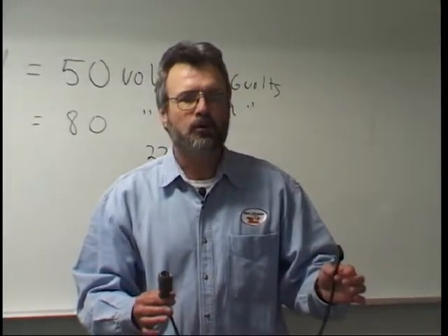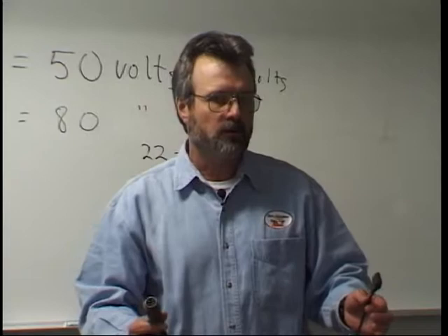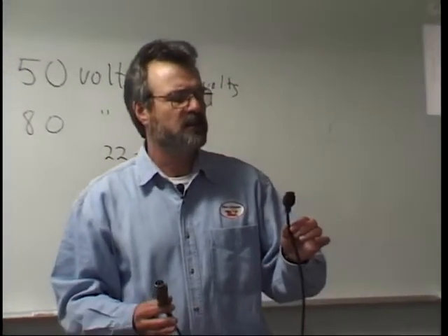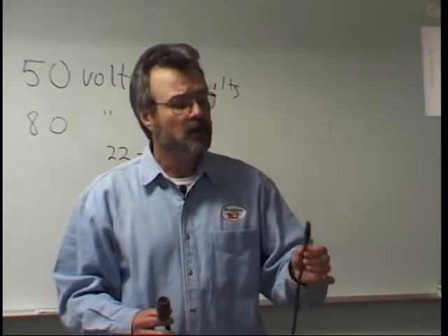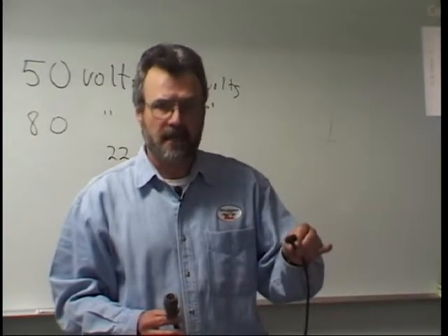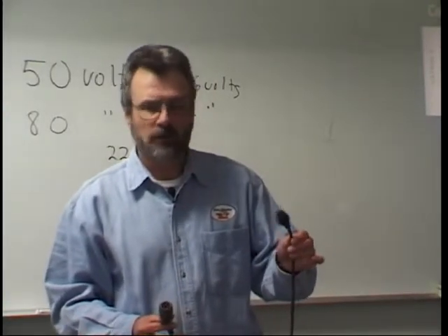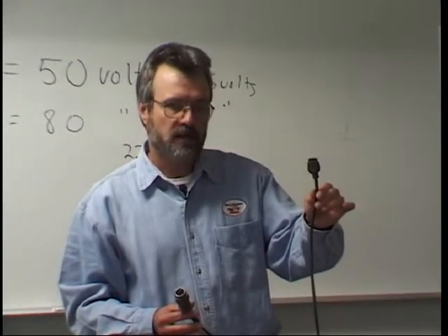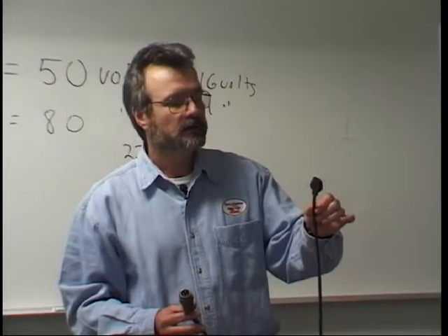And if you're ever having a problem, for some reason your gun stops working and you don't know why, this is the first thing you check, because these things are notorious for falling off, for breaking, or for not making connection. So that's just a heads up to you. In the real world, you could have problems, and this is the first thing you check, is where this thing ties into the gun. Okay?